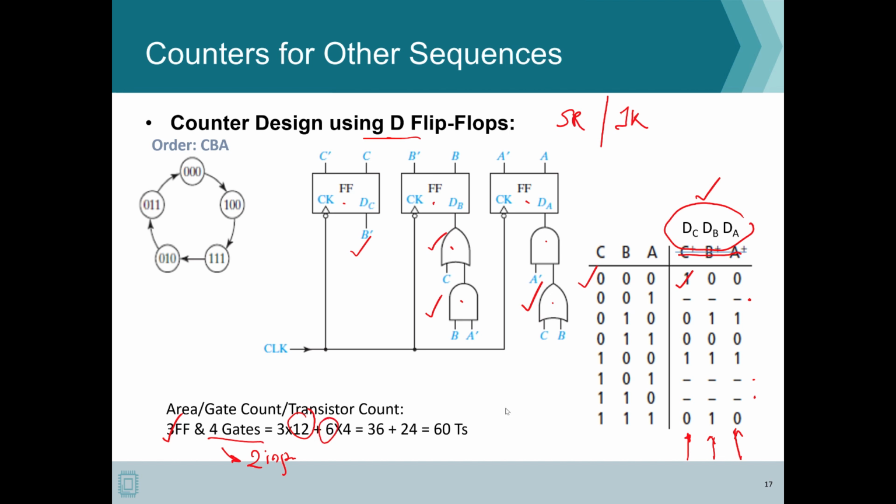So let's say if your implementation includes an AND or a NOR gate, then you need only 4 transistors to implement that. So anyhow, in this case we actually require 6 transistors to implement each one of them. So you have about 24 transistors in that case and 36 transistors in that case. So in effect you need about 60 transistors for this design.